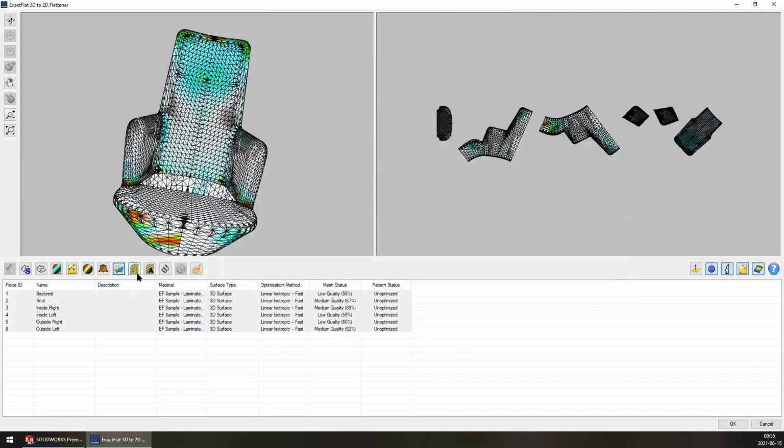So our next grouping of icons here are our remeshers. We have our uniform remesher and our adaptive remesher. These two tools have the exact same goal. They are used to analyze the curvature and the 3D shape of a mesh and produce a new mesh over top of the original with a lower polygon or vertex count. The two remeshers function slightly different from one another.